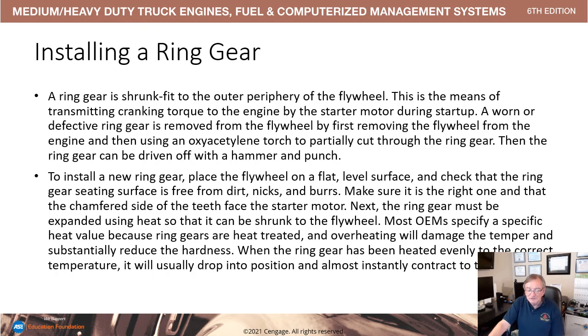Ring gears are generally done in specialty shops. It's really not done in regular service shops, and you basically submit the flywheel as a core, and they will do the precision welding that's necessary to recondition the flywheel so it can go back into service.